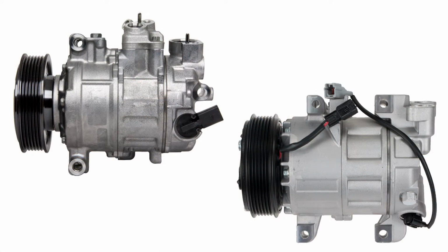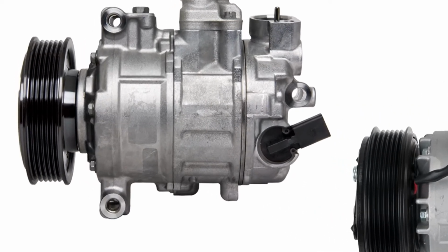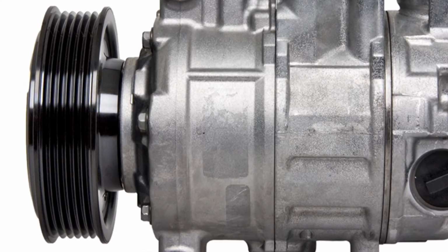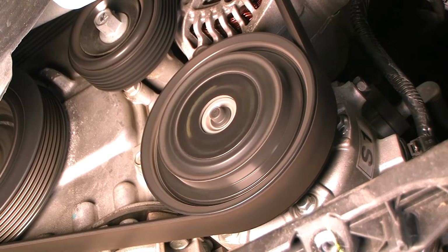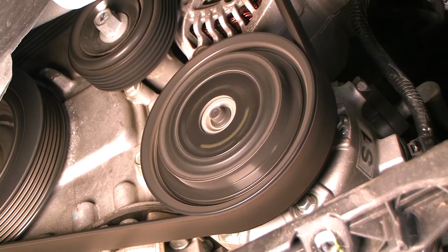First, there are two basic versions of ECV compressors, which can sometimes lead to confusion. Most early versions were clutchless. They do not have a conventional electric clutch. This means that the compressor shaft turns all the time, even when the AC is off and it's 40 below. To the naked eye, the compressor appears to be always engaged.